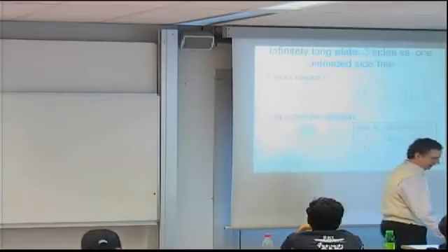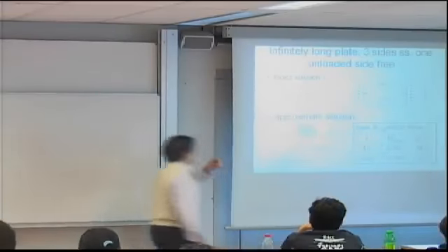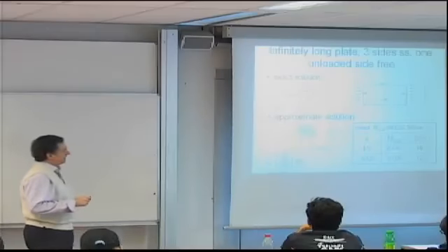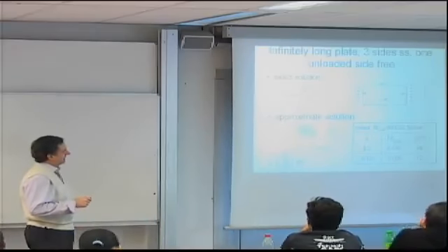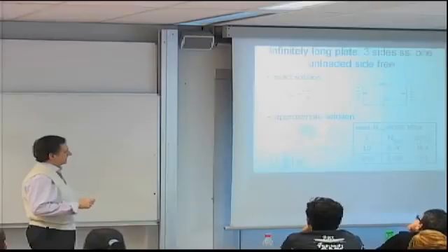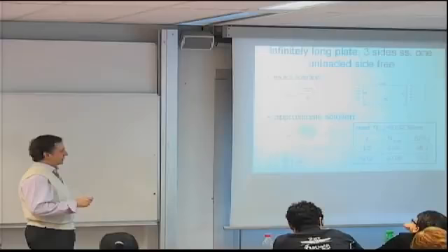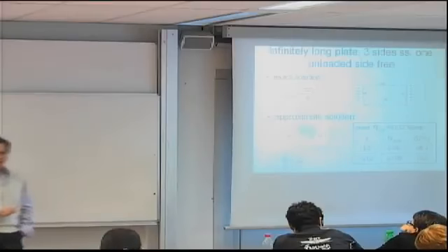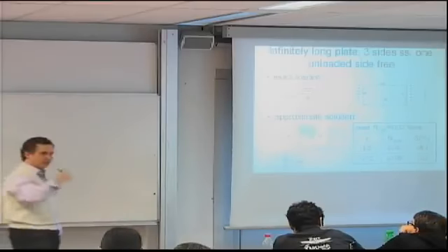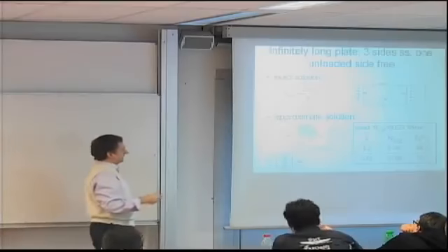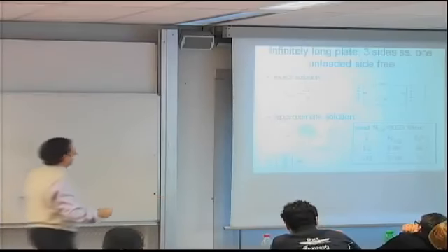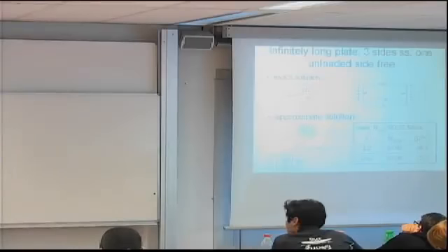Turns out, and I'm thinking to give you this as part of your final project a little bit, the buckling load for an infinitely long plate with one free edge is given by this quantity, 12 times D66 over b squared. So the only term of the D matrix that appears is the D66. D11, D12, D22 do not appear. And as I was saying, because the plate is infinitely long, any length dependence will be in terms of the width, which is finite, b.